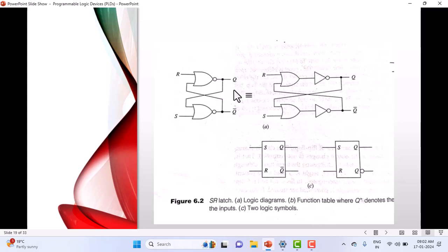You all forget. When both are 0, it's 1. Rest all are 0. So what is common in the entire NOR gate truth table if you observe it? If any one of the input is 1, output becomes 0. That's simple logic. Don't look too much at the NOR gate itself. If any one of the input is 1, output becomes 0. Understand? Let's not look at the special one here.